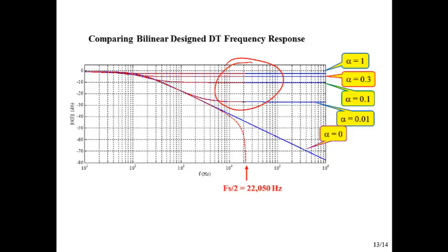This isn't quite high pass, it's a treble cut filter, but it's what's known as a shelving filter. So in a sense this is like a high pass filter, and you see that the bilinear transform works really well for that. If you were to zoom in down here, you'd see a little bit of error, and I'll leave you to run the code and check that out.